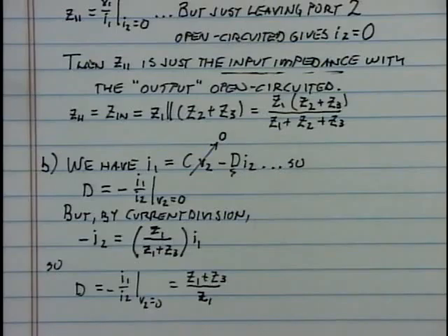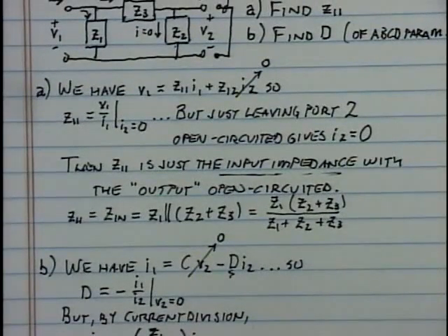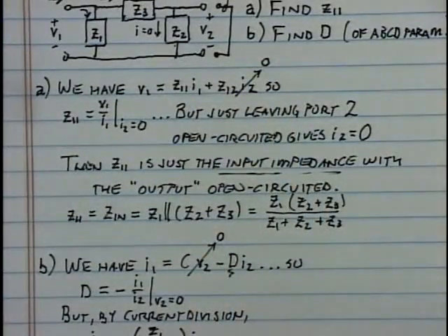They're all going to be in terms of either calculations or measurements in terms of open circuit on one or another of the ports, or short circuit on one or another of the ports, depending on which variables you're trying to zero out, get rid of in the set of linear equations defining the parameters, so that you can solve for the other of the parameters that's in that particular equation.